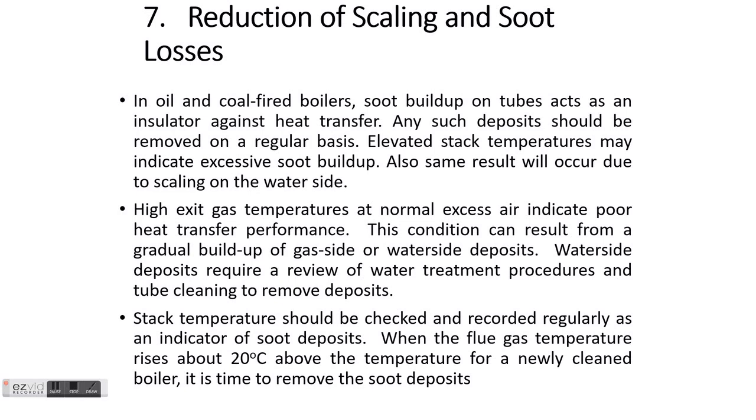7. Reduction of scaling and soot losses. In oil and coal-fired boilers, soot buildup on tubes acts as an insulator against heat transfer. Any such deposits should be removed on a regular basis. Elevated stack temperatures may indicate excessive soot buildup. Also, the same result will occur due to scaling on the water side.